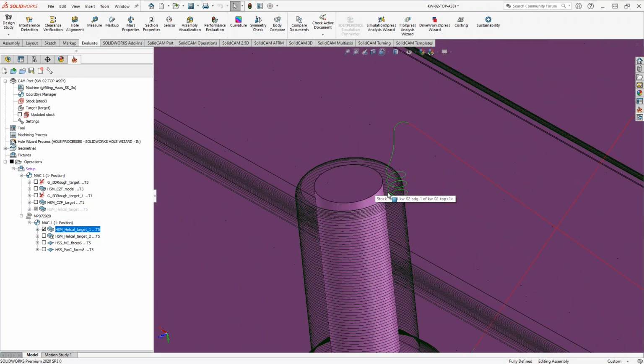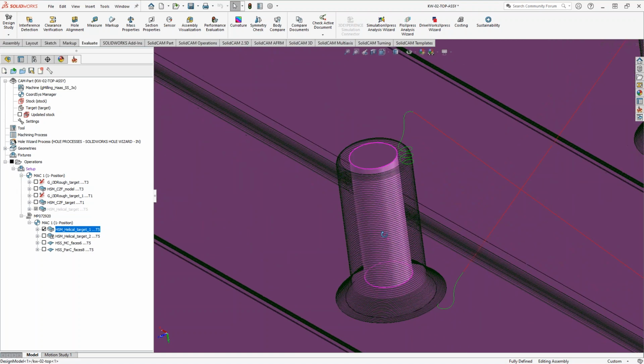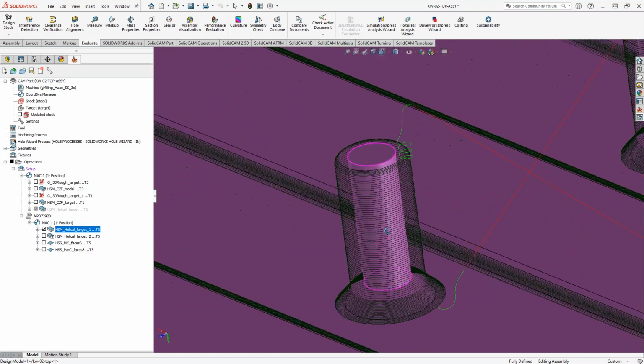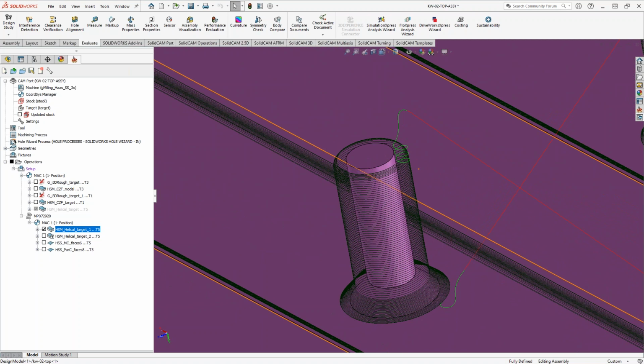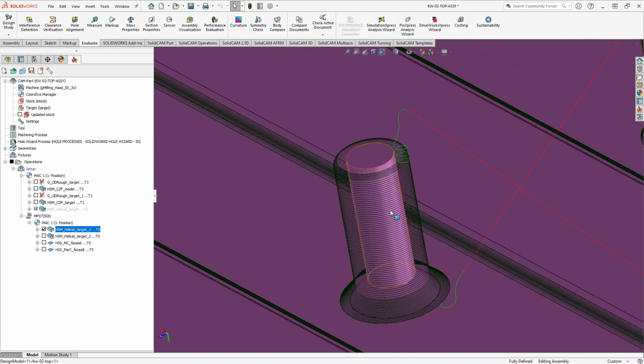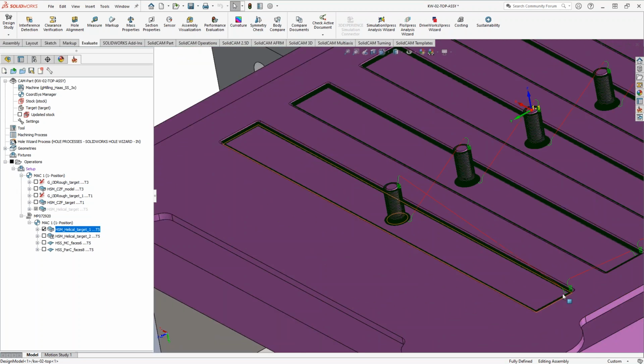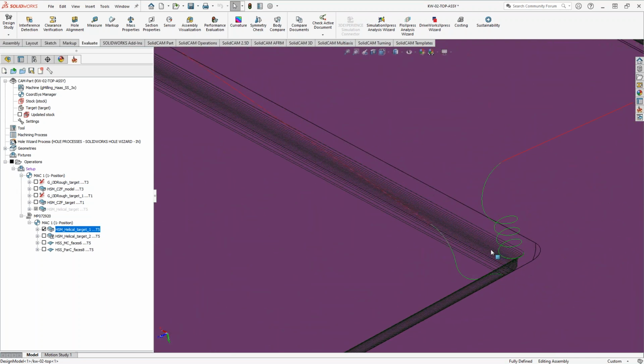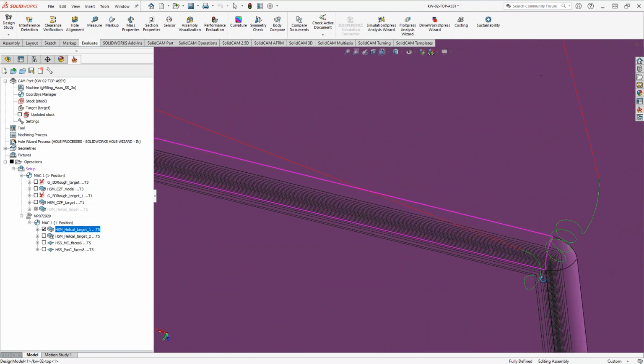Now with this, you get those helical entries. You get a helical toolpath that goes around that post like that. And that's pretty much where I would have just applied helical or spiral or any of those kind of guys if I'm looking to just do that post like that. But because the boundary was including this pocket, it actually ended up doing those corners for him.